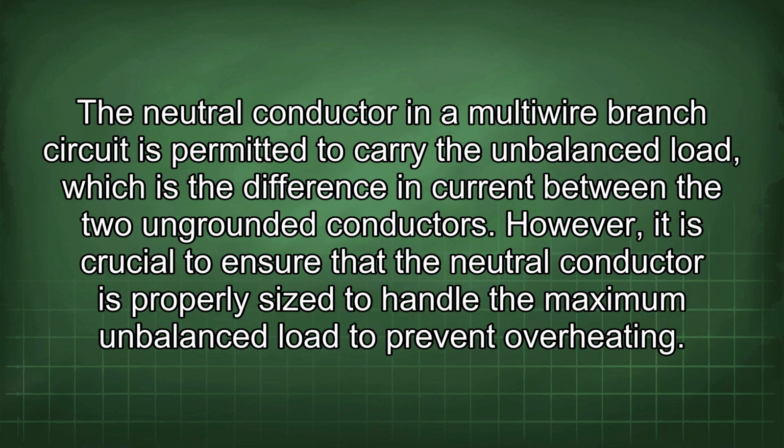The neutral conductor in a multi-wire branch circuit is permitted to carry the unbalanced load, which is the difference in current between the 2 ungrounded conductors. However, it is crucial to ensure that the neutral conductor is properly sized to handle the maximum unbalanced load to prevent overheating.